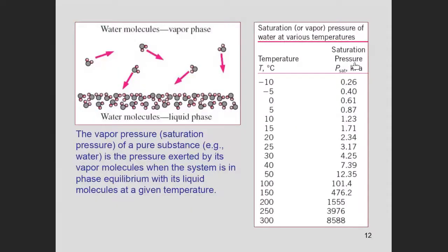Do you remember in your thermodynamics, guys? So for example, let us assume that day, assume you are working in Marafiq, okay? Assume you are working in Marafiq, and that day the weather tells you that the temperature is about 30 degrees. That means, gentlemen, the pressure in the pipeline, you have to watch, the pressure in the pipeline should not drop below what, guys? Below what? 4.25. If it drops below 4.25, cavitation will take place in the pumps.